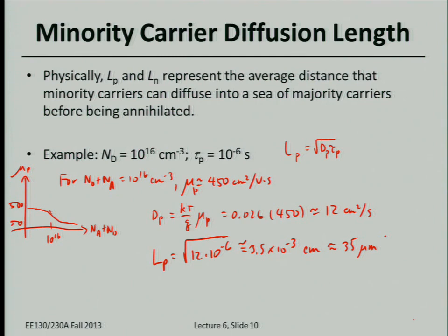The key here is that you have a p-n junction, and the body of the transistor is also pretty small. It's much smaller than a micron. So the diffusion lengths are actually quite long compared to typical semiconductor device regions nowadays. We'll come back to that. That's why later in this class we'll talk about short base diodes. In other words, there's a special case: if these semiconductor regions are very short, much shorter than the diffusion length, we actually can't use the minority carrier diffusion equations anymore. Okay. Any questions in general about this example?